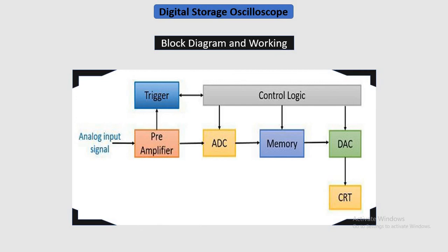The size of the memory unit determines the number of samples stored in it. One can alter the length of recording by changing the sampling frequency of ADC. In the case of digital oscilloscope, many different input channels are used, but the memory available to each channel gets reduced. When all the channels share a common store, this is done through multiplexing.